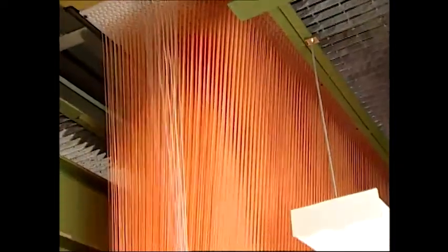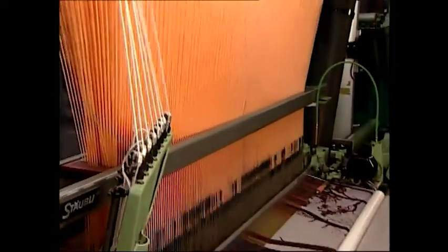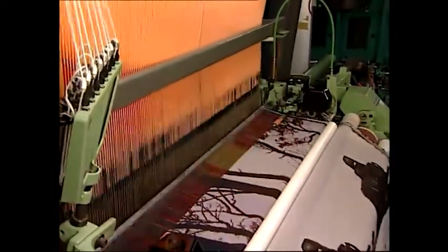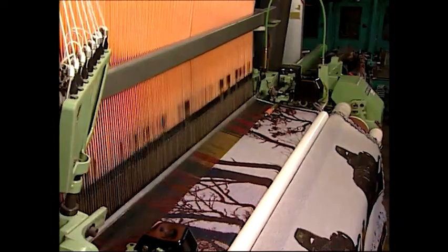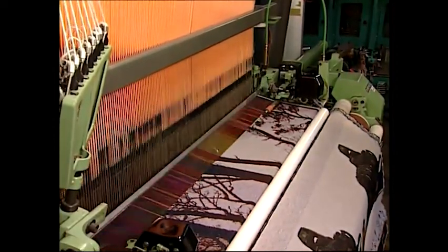Jacquard shedding exhibits control on each individual warp yarn independent of all other warp yarns. Up to 12,000 warp ends can be controlled. These systems can employ mechanical or electronic devices to actuate the warp ends. Design capability is virtually unlimited. Pattern areas can equal the width of the fabric and are almost unlimited in the length.